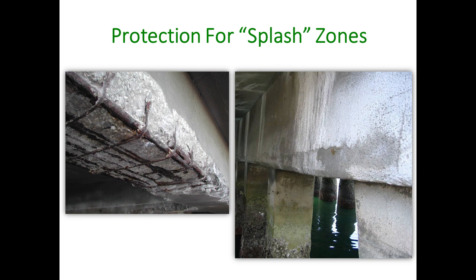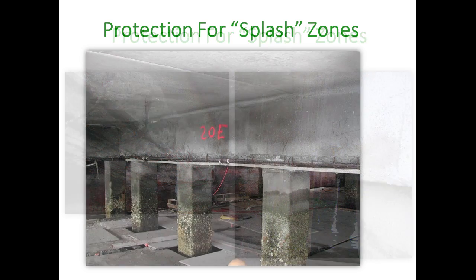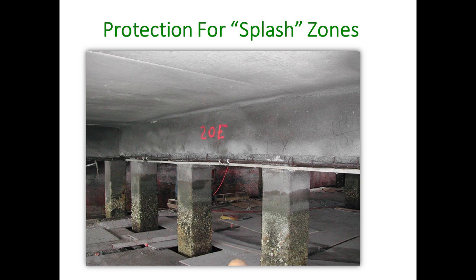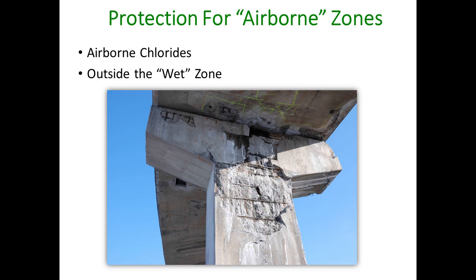Another area where this can be used is pile caps. You'll see a lot of pile caps that are closer to the water, and they get periodic wetting or splashing, and there are various systems for this. They're an activated system, and traditionally they're installed in an overbuild and poured back. Like I said, there are a number of different systems available, and as I mentioned before, there are also powered systems or impressed current systems available for this.